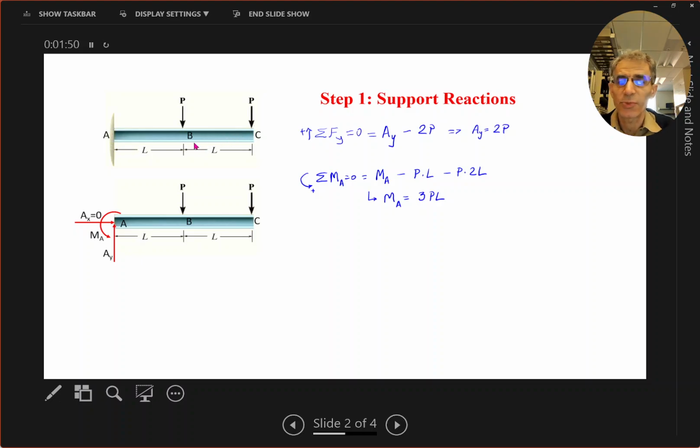By the way, this problem I work on is symbolic, as we can see. All these problems have three steps. The first step, of course, is to solve for support reactions. So we have to isolate the beam. Well, we can see that being a cantilever beam with a fixed end at point A, we have these three reactions there in the plane.